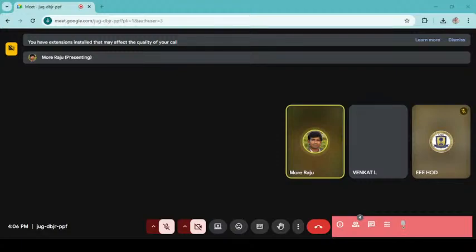In the stepping motor, there is no carrying of winding on the rotor side. The stator flux causes the rotor movement through a single step, so that the reluctance seen by the stator field is minimum and the stator flux linkages are maximum for the given stator current. We'll see that through the diagram. When the diagram comes, you will clearly understand.